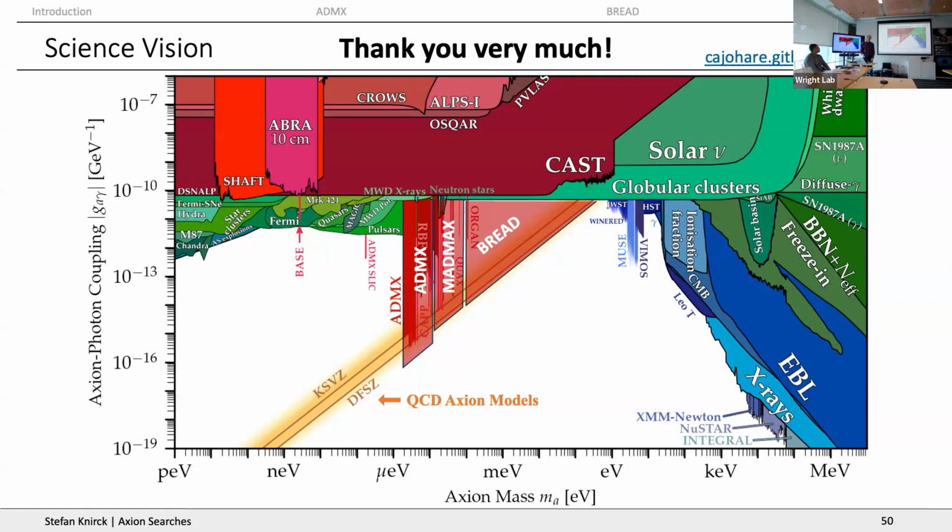So far we haven't seen any signals that impede us. In the GigaBREAD at the magnet at Argonne National Lab, there's actually an RF accelerator right beside it, so we did have to do active vetoes. We had a second data acquisition chain, which mirrored the one that is taking data, but with an outside antenna. Whenever that antenna saw a peak in a certain frequency range, we shut off the other chain in exactly that range and vetoed those signals, and that vetoed everything we were worried about.